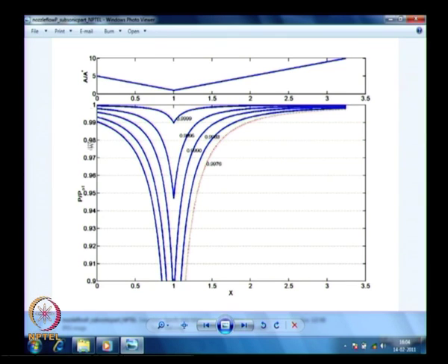I am showing here the nozzle which I have calculated the pressures for. I am showing you here A by A star, where star is the throat condition here, where it is 1. A by A star is 1 at this location. This number does not mean anything really, the x axis is just some distance. You are going to see that it is starting from A by A star of 5 and goes to A by A star of 1, and then it goes back to 10 at some location.